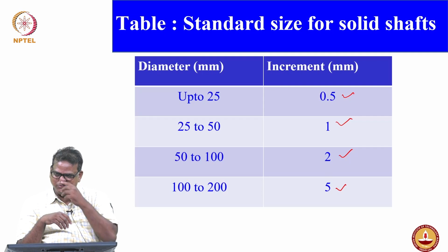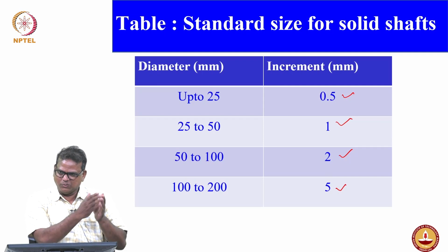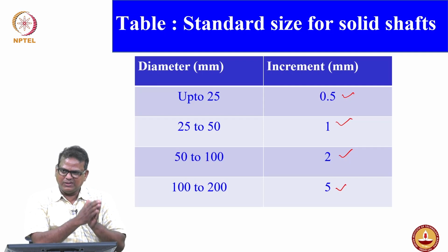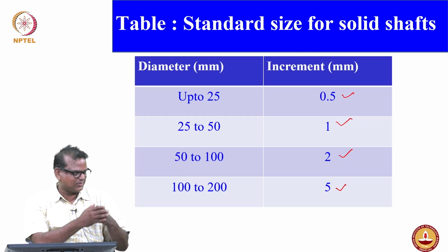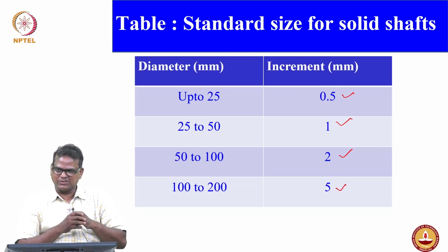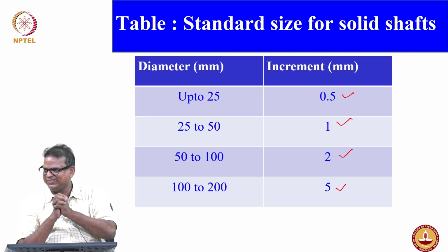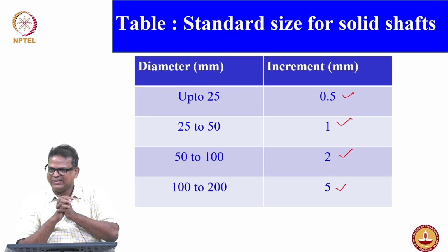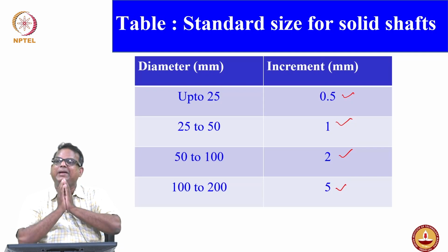In all the calculations we have chosen, remember, for pitting stress in the module calculation we gave the safety factor 1.5, 2, 2.5, 3, we have done that. Similarly, we have taken the face width factor psi, as structural support psi, with different values, and we got the relationship also, that is, finding the values. The question is whether whatever values or answers we got are correct or not, how would we check? What is the way to check? Or how are they related within the design constraint, within the design limit.